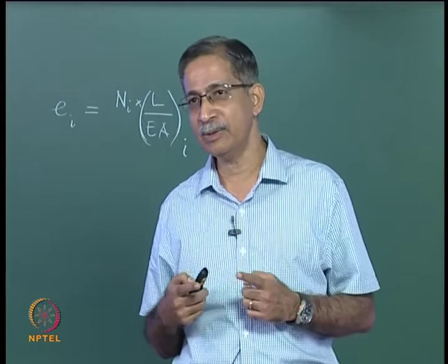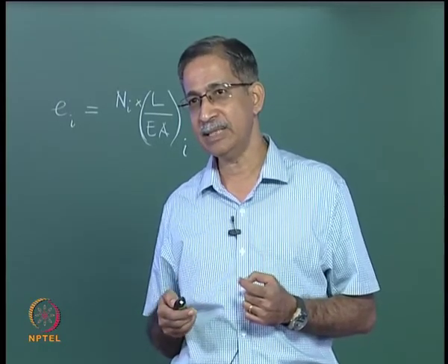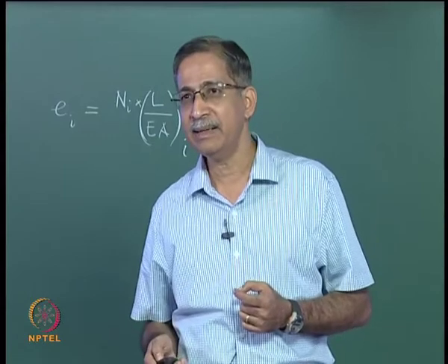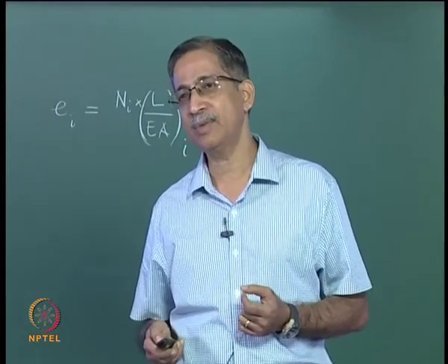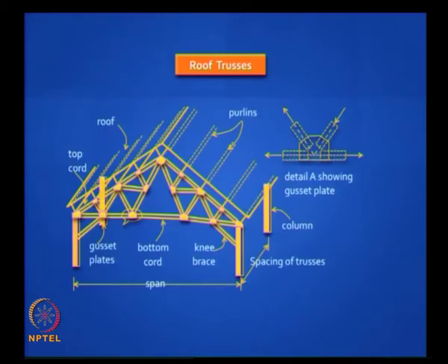So the only way to do that is to rotate AB about A and CB about B till they meet, and you can draw arcs or tangents to do that, and that is how you locate the joint geometrically. You can actually get the deflections that way, but we will find there are better ways of finding deflections.